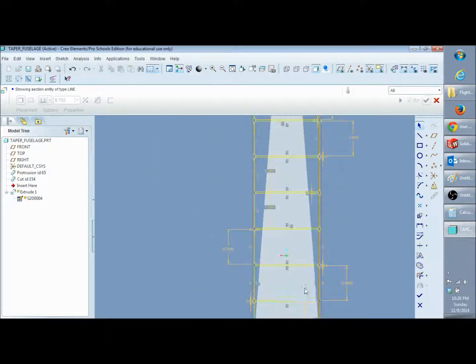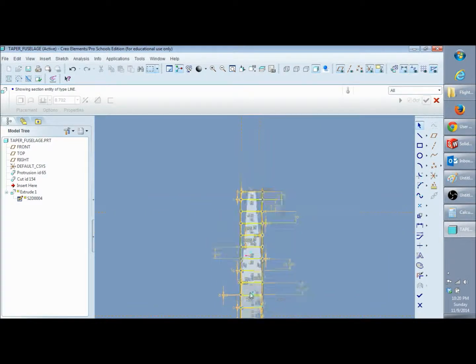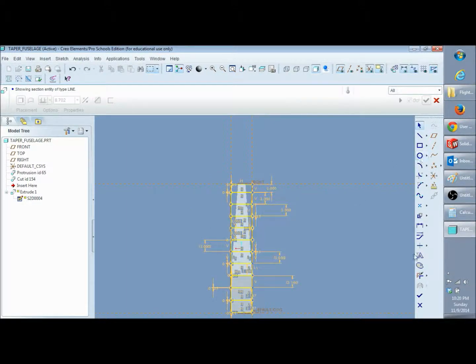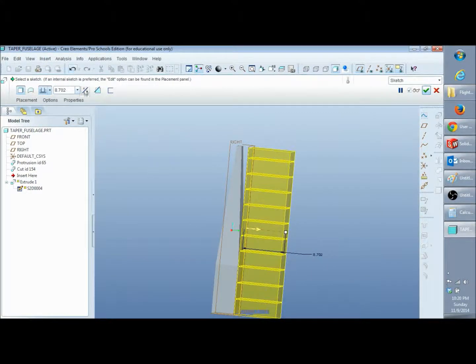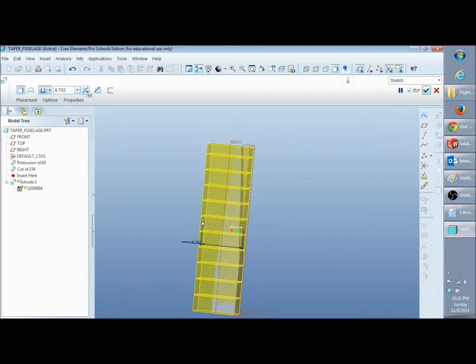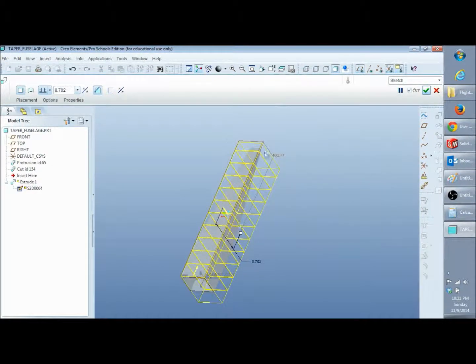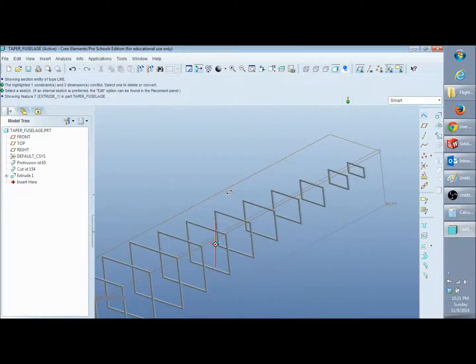So there you go. Now you've got a closer look back there, and all of these down to the flat, where it starts to become straight and not tapered, is good. Go hit OK. Notice that now it's creating solid shapes. Reverse the direction on that, and then do the remove material, just this button right here, and it should delete the model from the edges that you don't want. So there you go, you have the frame for your fuselage.